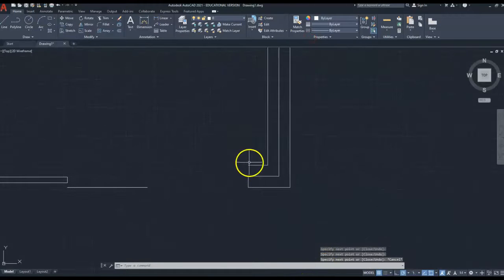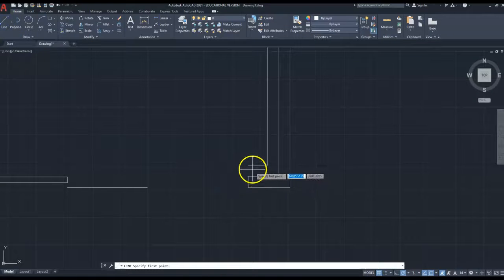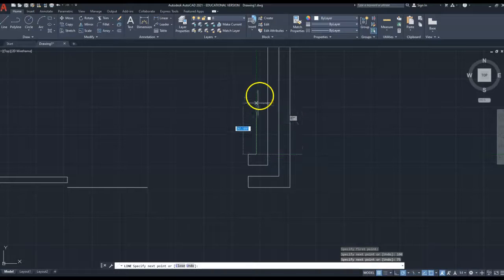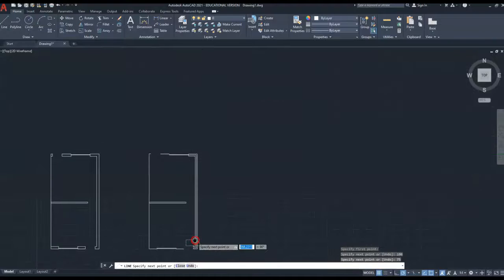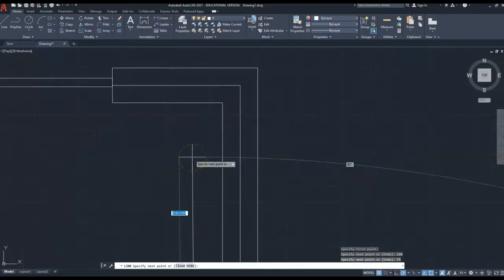So I'm going to go back down here, and this is where we'd have to change things because I'm not going to get into building regs or anything like that at the moment because that would be too much. But I'm going to go 100mm because that's my internal skin, and that's 175. So I'm going to go 75mm in, and I'm going to zoom out, mouse down, zoom in.